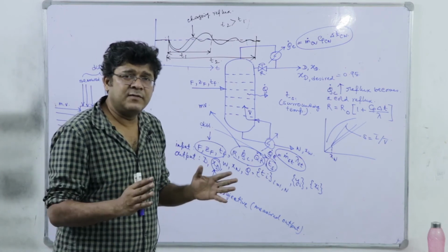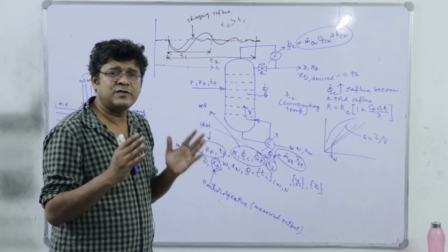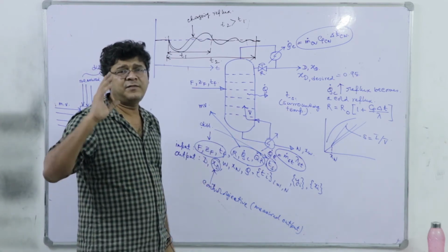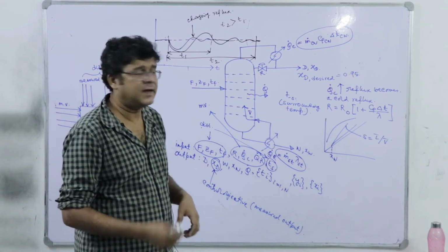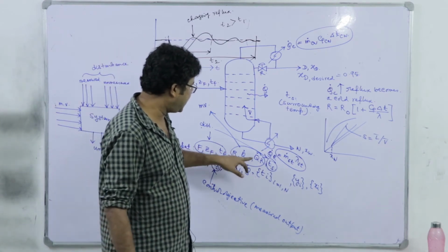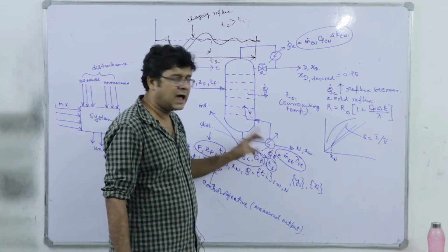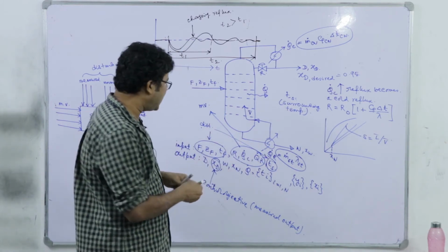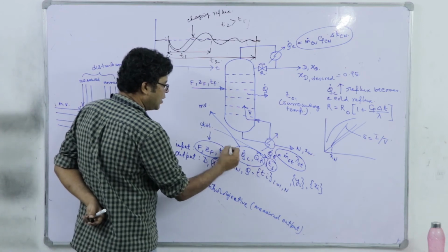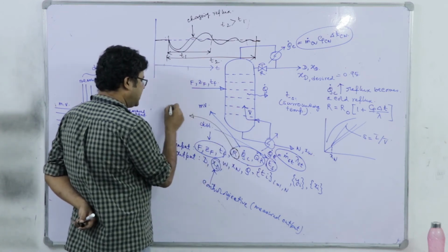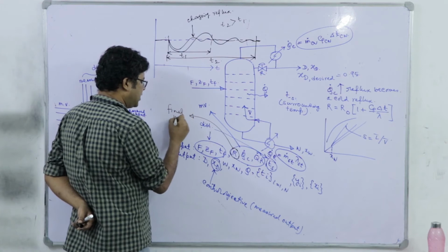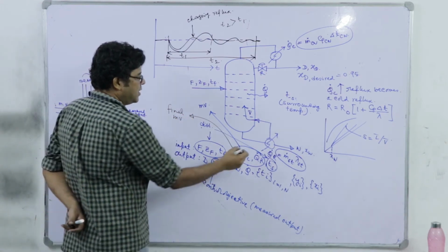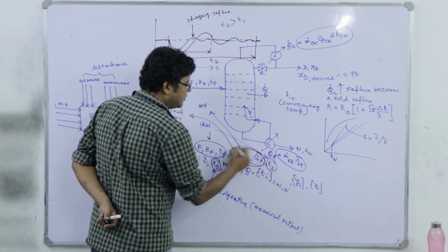So our objective will be to choose a manipulated variable which has the fastest influence on that device. So we will keep Q̇C as well as Q̇R at their design value, and we will choose R as my manipulated variable because we have only one control objective. So finally, the manipulated variable. Now once we choose R as the manipulated variable, Q̇C and Q̇R should be